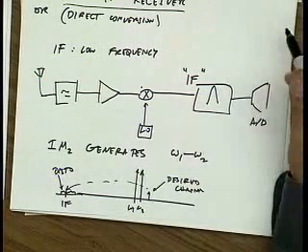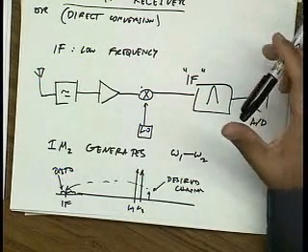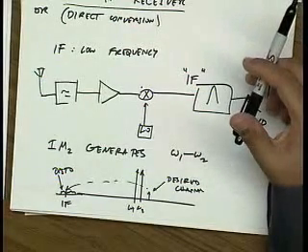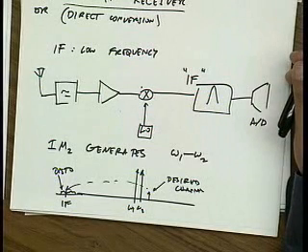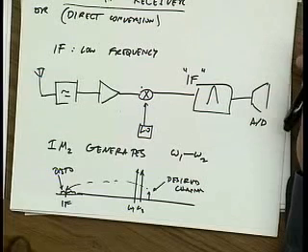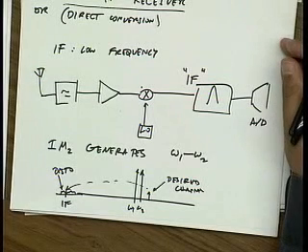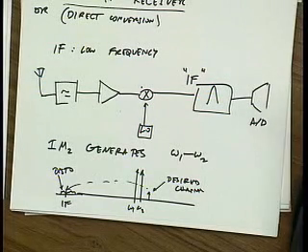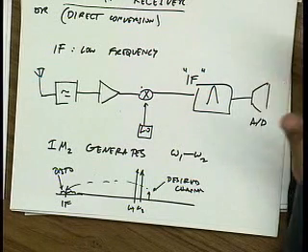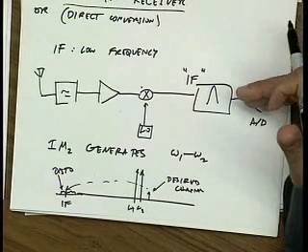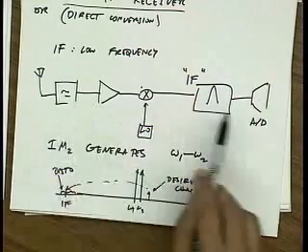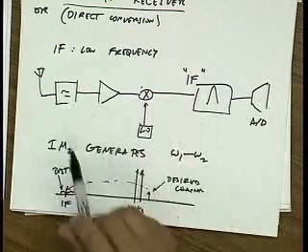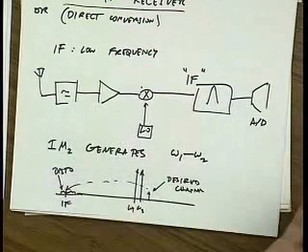Now remember last lecture, what did we say about odd order functions? Kevin? On polynomials, yeah. What was the nice thing about odd order functions? They don't generate any even order distortion terms, right? So if there's no even order distortion, we wouldn't generate any intermodulation. So in an ideal world, if we made all these signals differential, we wouldn't have to worry about IM2. Is that true?